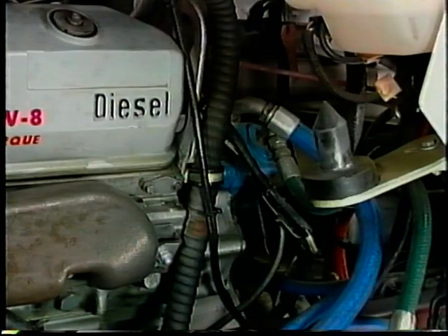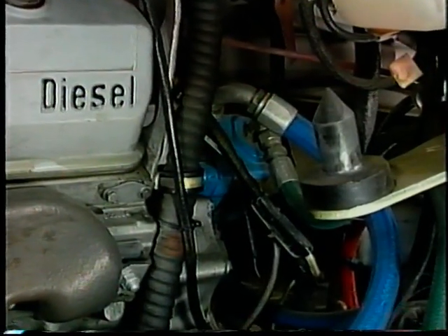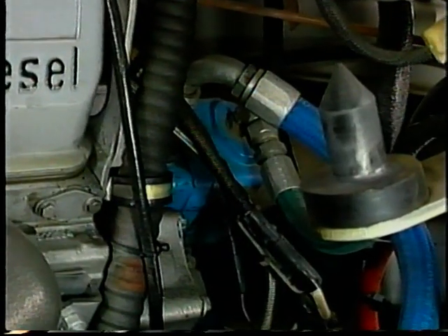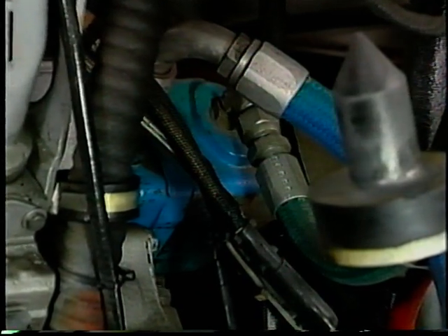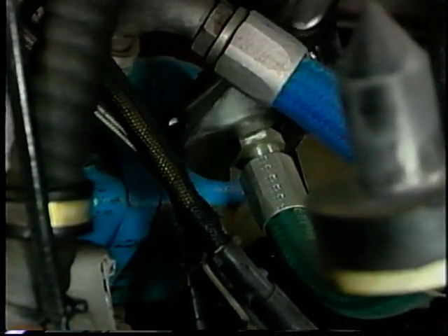The power steering pump will have to be removed and disassembled or replaced if the test shows low PSI and low flow indicating a defective pump. High PSI and flow indicates a properly working pump. Normal PSI, but more than 1 gallon per minute internal leakage, indicates steering gear problems.